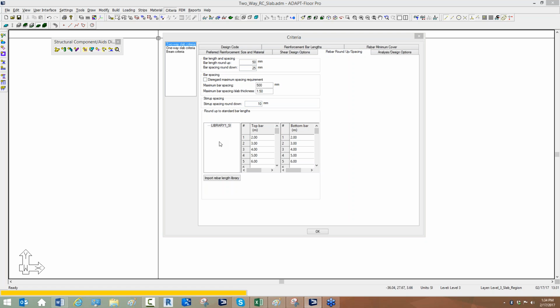So there's another question: when does the new and improved punching shear module come out? We plan on releasing it in version 2018, which is planned for this year. So it's technically the fall of this year as the tentative release date. The 2017 version of the program will be out in May, June of this year. That will include wall design. It will include tendon modeling improvements, being able to swerve tendons, being able to modify the CG of tendon groups on plan, showing the CG and just modifying it instead of having to open the tendon dialog and generating the modifications there.